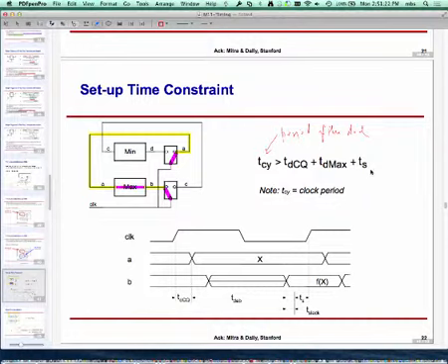Separately we have to worry about whether we remain stable for that stability period. So right now all we are saying is I want to make sure that the new value that this bottom flip-flop should read is ready before that required period of stability begins. Right?